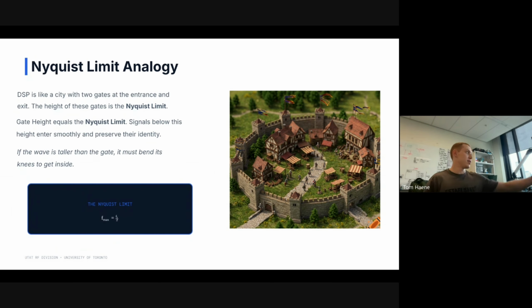And that's Fs, the sampling rate. And what I'm saying here is the maximum frequency that you can represent as a digital one without losing information is your sampling rate over 2. And if you are sampling a signal that has a higher frequency than that limit, you lose information. It doesn't work. So it's all about frequencies. Okay? I'm going to explain this again a few times with the analogy, but that's the initial idea.